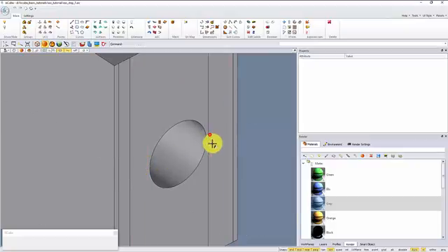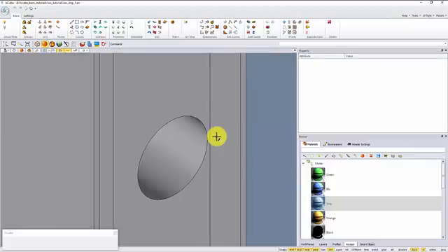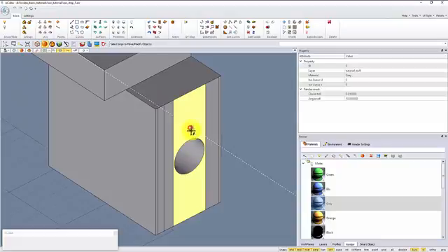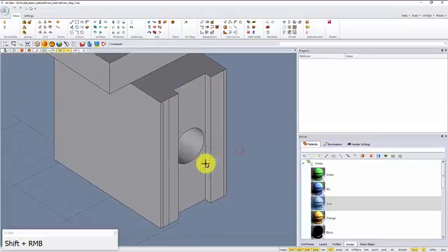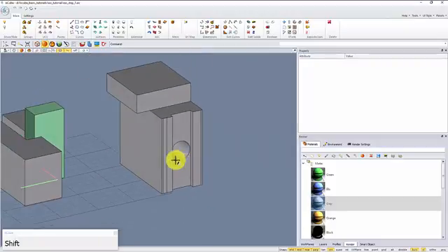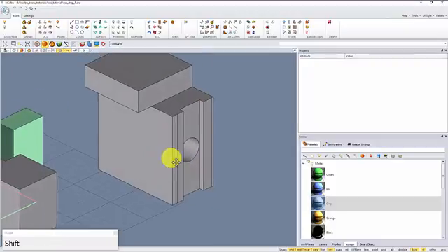So we can have this distance of 0.1 meters. If I recall the tool again, I stay here and input 0.1, I can have a 0.1 from that curve and we can pull it inside. So this tool was the drop parametric curve, drop curve.